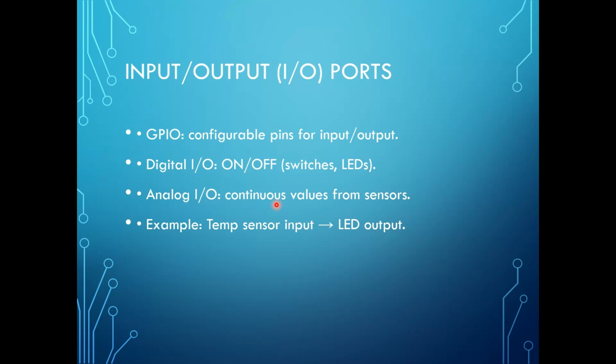So for example, Arduino reads an analog temperature sensor, processes it, and switches on a digital fan. Suppose you have a range: if your temperature goes beyond 30 degrees and you get the data from the sensor that it's 31 degrees, it will switch on the fan. The fan will be on. That's the process of these boards, and you can make it according to your project. GPIO is what makes MCUs, meaning microcontrollers here, interact with the real world.